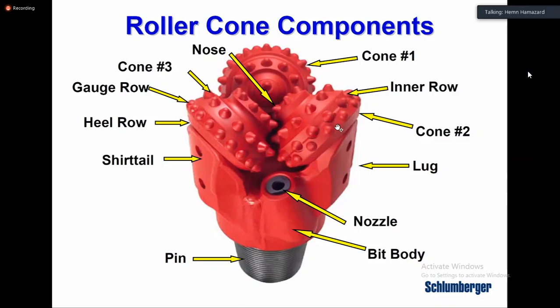As if you pull out the bit and then you analyze what has happened to your bit, and you check if the biggest share of the damage has occurred to your outer cutters or the inner. If it is outer, that means these cutters are responsible to touch the wall of the well, but the inners are mainly responsible for making the hole, and the outers are mainly doing something like reaming, we can call it.